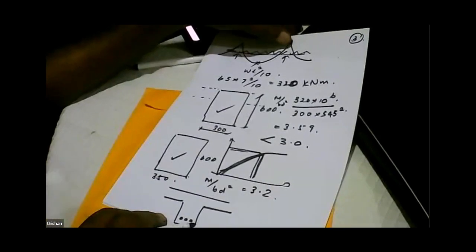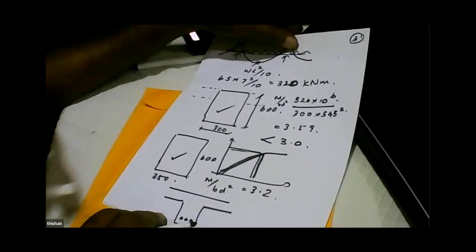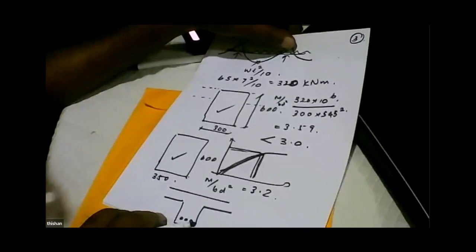So you would have seen all these rules of thumb given by various people. But I select the general arrangement drawing so that all beams will be singly reinforced. Why? Doubly reinforced beams are very expensive. What is the reason? For concrete, we don't pay for the environmental cost. For manufactured steel that is imported, there is a huge amount of embodied energy in it. So steel is very, very expensive.